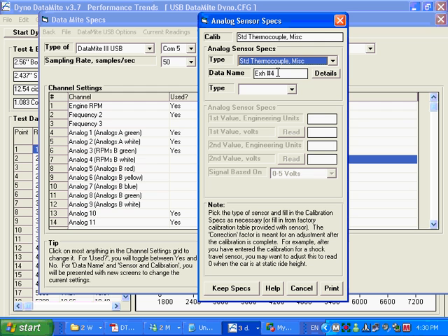And you could call it exhaust number 4, but it's not going to be graphed or shown in the current readings on that. The gauge is on the right side, and there's some special graphs that we do on just exhaust thermocouple. So if it's not a true exhaust thermocouple, you may want to call it a miscellaneous thermocouple and put whatever name in there that you want. Now, if you pick a thermocouple, you got a choice here.